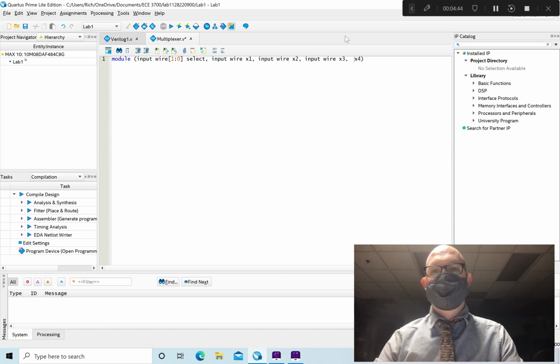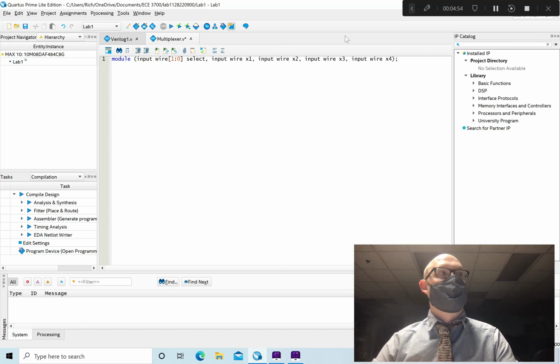The default assumption is wire if you don't put wire, but it's best to specify. It's just best practice, because there are regs and there's bidirectionals and there's a few other types that you can use. All right. And then a semicolon after that module. And then I like to make a new line there so I have some space to work, and then I'm going to type end module and another new line so that I don't forget to close my module.